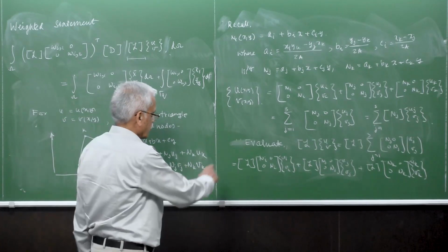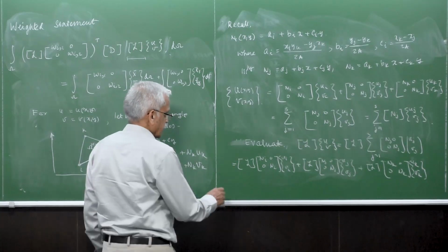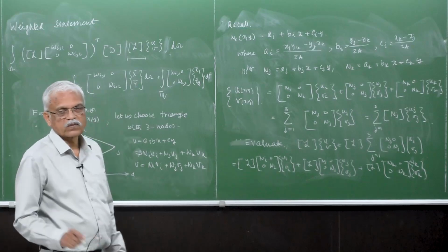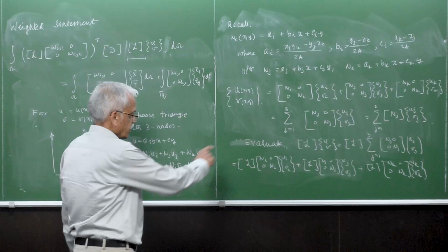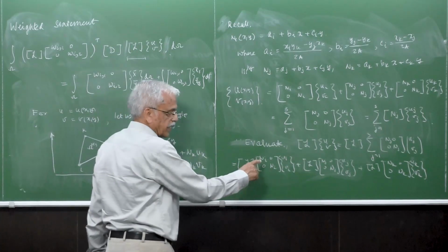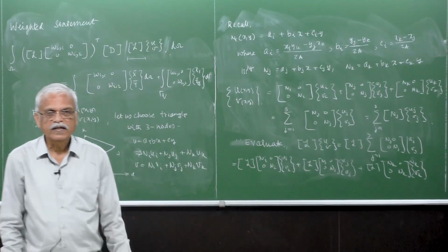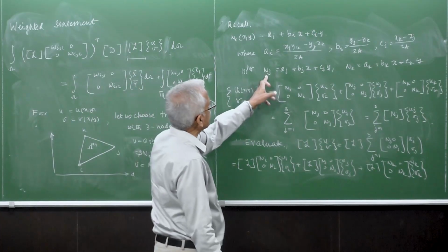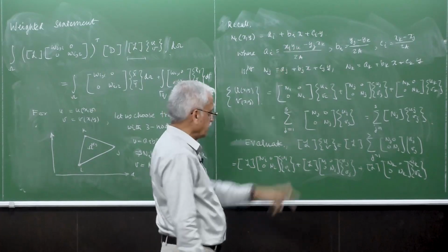And so if you expand this one, for example, L has ∂/∂x, 0, 0, ∂/∂y, and ∂/∂y, and ∂/∂x. So if you operate it, the derivative of Ni with x will be ∂Ni/∂x. So recall it. If you go back here and take the first derivative of Ni with x, it will be simply Bi.